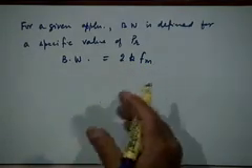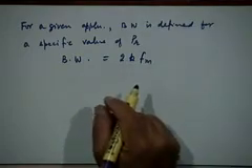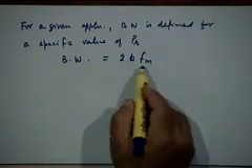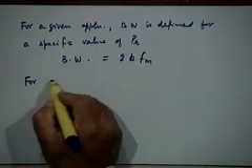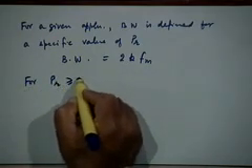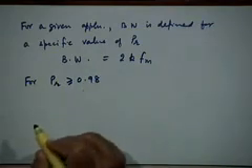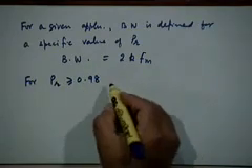Whatever value of k would give you that value of PR would then imply that the bandwidth is 2k f_m. So for PR to be greater than or equal to 0.98, that is the 98% bandwidth.